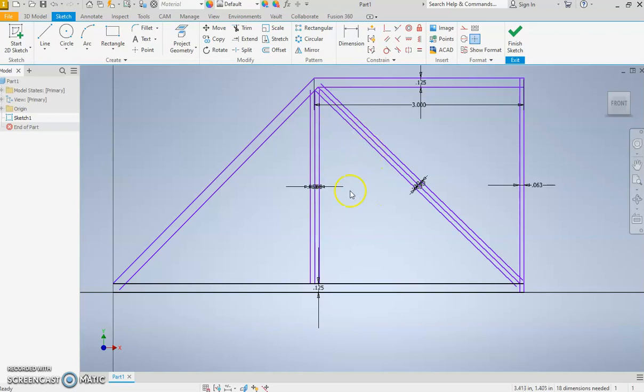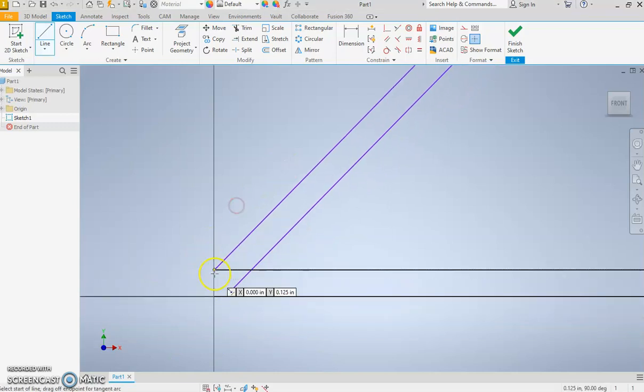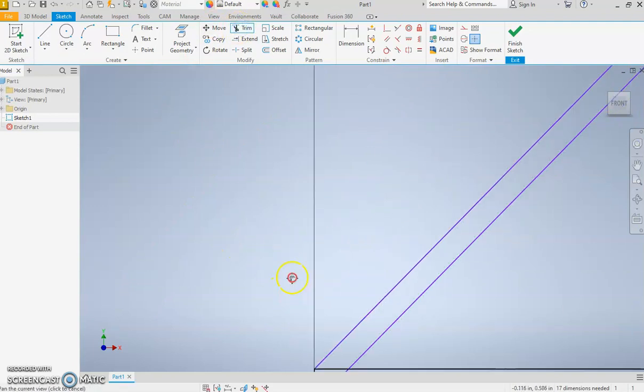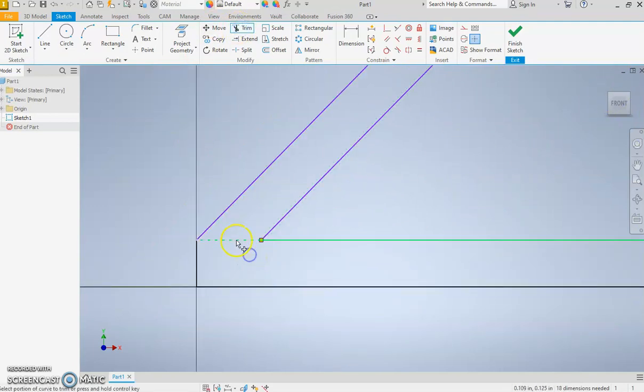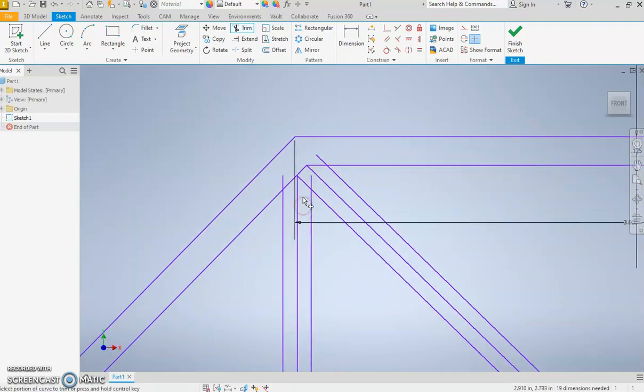But now obviously I have some trimming to do. Also, I'm missing a line down here, if you noticed. I know you did because you're paying attention. Smart too. So I'm going to hit trim. And a couple ways I could trim. I just click on my pieces, because we want this to be open. Or I have my fancy way where I left click and hold, and I could do this ziggy little pattern here, and anything that touches it will be trimmed.